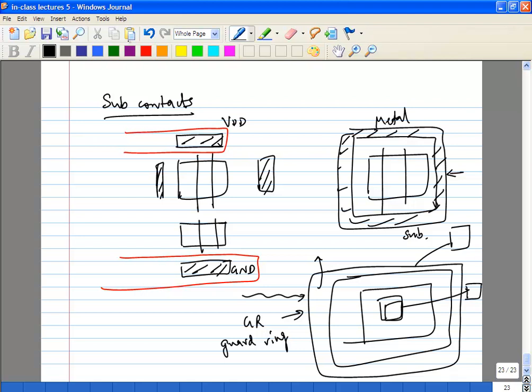We will connect those two contacts. Sorry? We will connect those two. Okay, so these two will be pads. So you'll have a bond ring. So the idea is to increase the impedance between those two paths, so that at any time the noise current has a choice between which paths to flow. It will flow through the low impedance path.